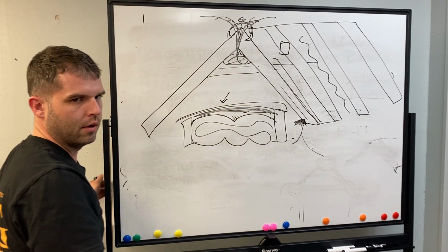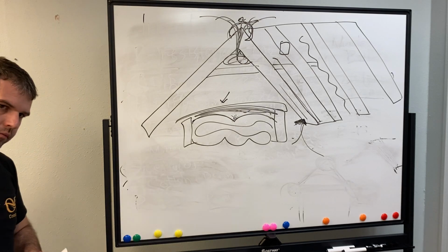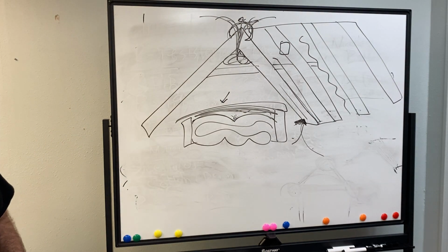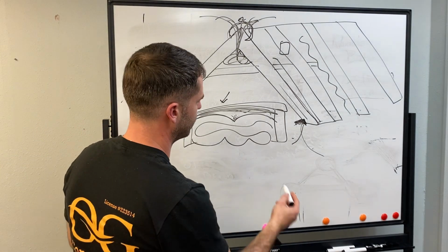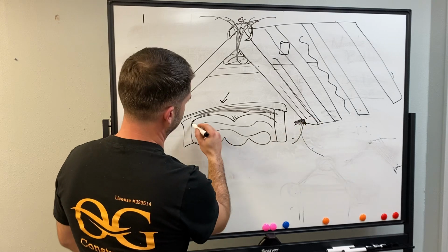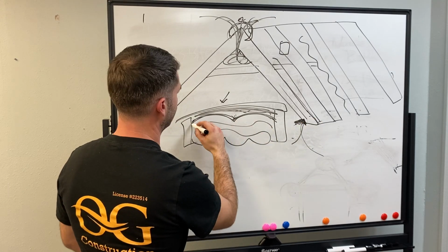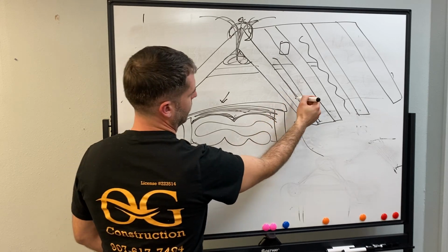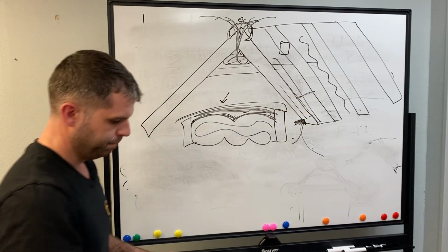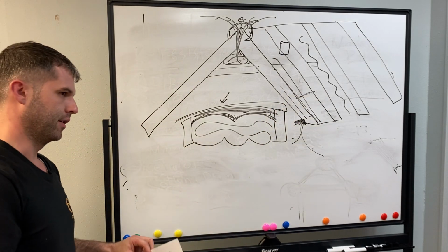I've seen people use R19 on a 2x8, and then it doesn't expand as high, and so it leaves a gap on top. Right, that's exactly right. You have to use a smaller one. I mean, I would still use an R19. I would just put, instead of the foam one, something that's stronger to keep that space between the rafters. So that's very important on a vaulted ceiling.